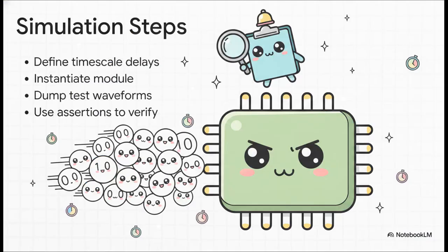All of this intense precision builds into what we call a full test bench. A test bench is basically just a piece of software designed to brutally stress test our hardware code. We define a timescale, instantiate our adder module, and then write code to rapidly drive random numbers into the input pins, complete with simulated time delays. Crucially, we write assertions, which are automatic checks that instantly flag an error if the physical hardware simulation ever dares to disagree with our expected mathematical logic.